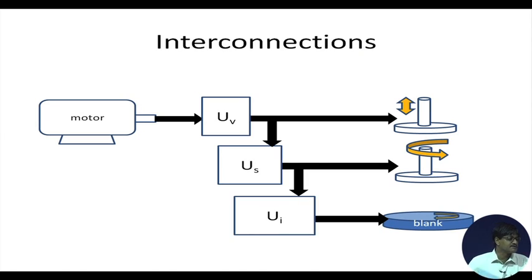Okay. So, now let us cross check that. How is the ratio of the cutter rotation and the workpiece rotation affected? So, in the loop that we have between cutter and the workpiece, this is the flow of power. Here we were moving backwards, here we move forwards, we reach UI and then we reach the blank. So, we understand that the ratio of rotations of the cutter and the workpiece or the blank can only be affected by elements which are present in this loop.